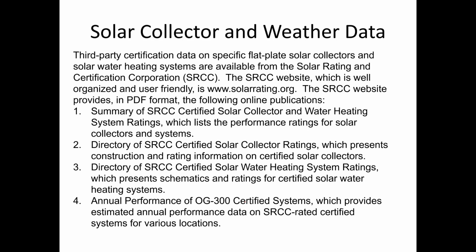So again, you take this data from the solar collector, you take insolation data, and then you use both in order to evaluate the effectiveness of a solar collector for your specific application. There's third-party certification data on specific flat plate collectors. Solar water heating systems are available from the Solar Rating and Certification Corporation, called SRCC.